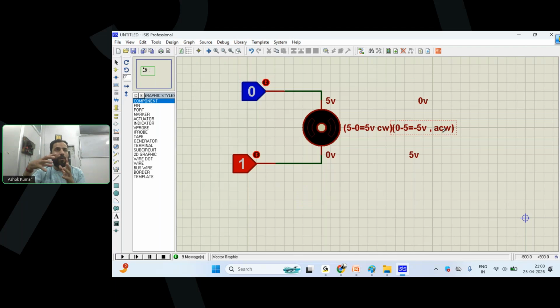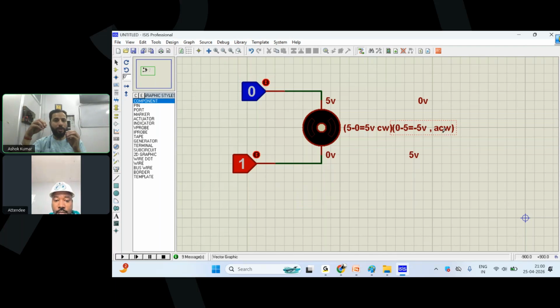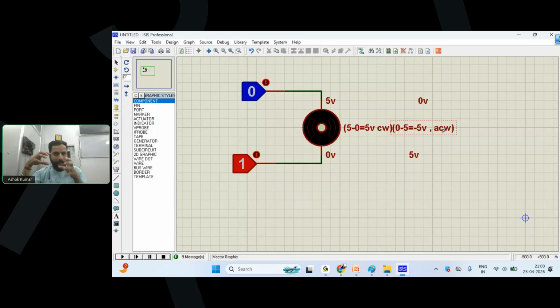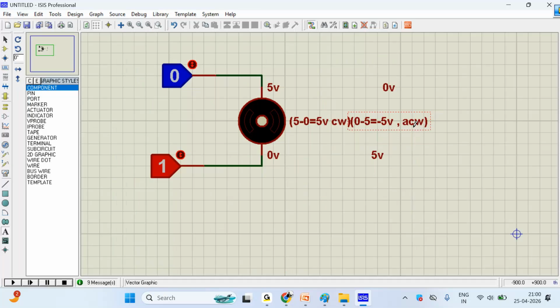But if you have to go left and both sides should be working, then the concept is a bit different. For a left turn, move the left motors anti-clockwise and the right motors clockwise. This will take a sharp turn, which is called a 360-degree rotation, also called a drift. And when you go right, move the right motors anti-clockwise and the left motors clockwise. So this is a sharp turn for the right side.